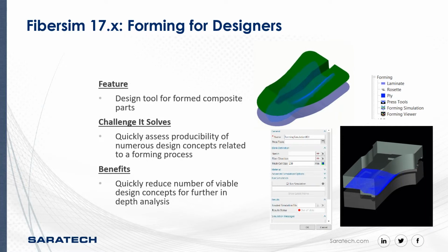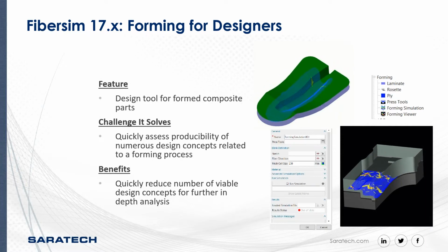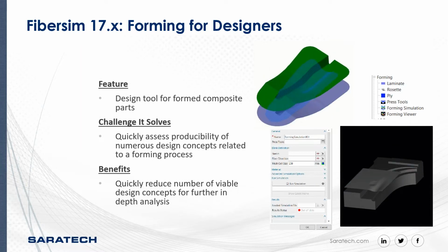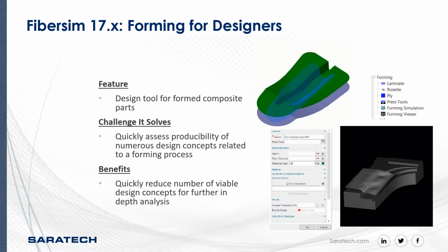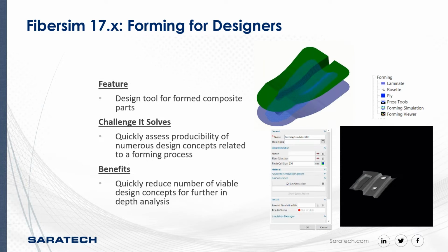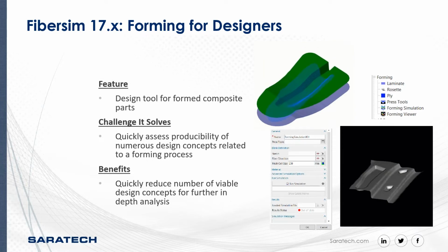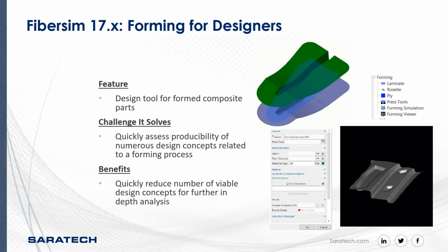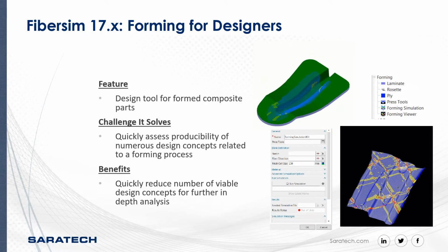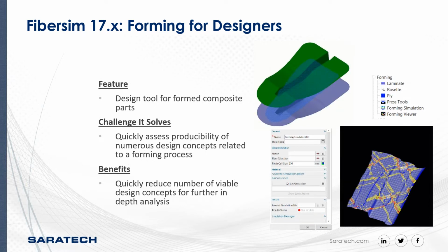When you actually take forming and then turn it into something, basically Fibersim can simulate that match mold process. And you can see here in these animations, it's taking the blank, it's a pinned blank that's being compressed within the 2 sets of tooling, and it's attempting to identify whether that compression is actually going to work for that part shape. Okay, so the forming capability allows you to define the tooling, the timescales, and everything that you need in order to do this type of simulation.